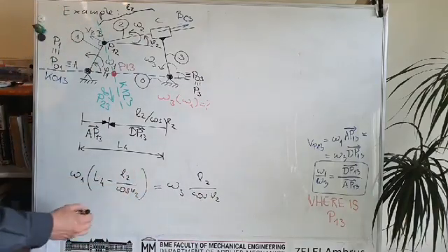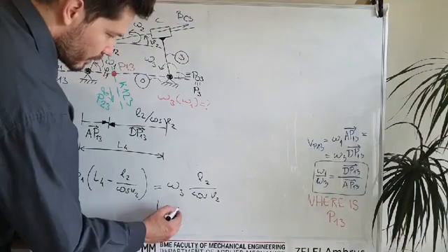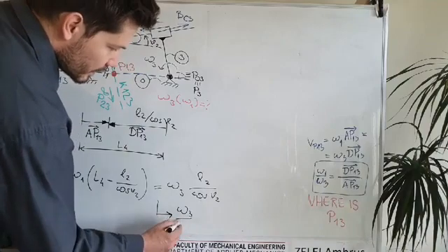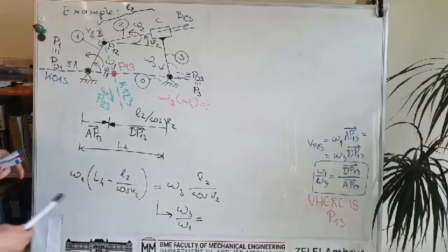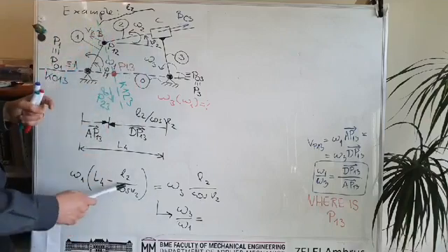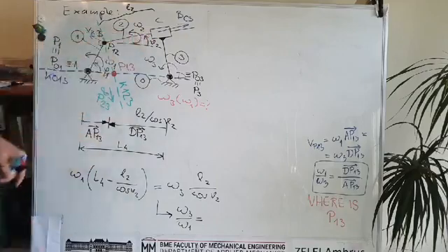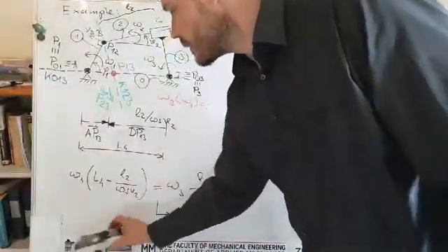And from this formula we can get the ratio of omega 1 and omega 3. Okay, so we can finally compute the ratio of these two angular velocities. And here we see that we have to do some additional geometric calculations. So we should calculate this distance and also this angle, so there are some additional calculations, but basically this is how this geometric approach works.